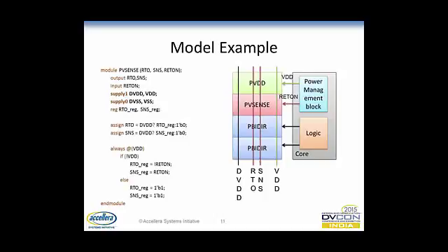Now in this case, if you want to simulate this type of environment in your RTL, there is no way that you can have correct functionality unless you have the VDD and power pins in your Verilogs. But your RTL doesn't have the PG pins, so you cannot simulate it. That's a problem, and that's when the need for an integrated power-aware model comes.